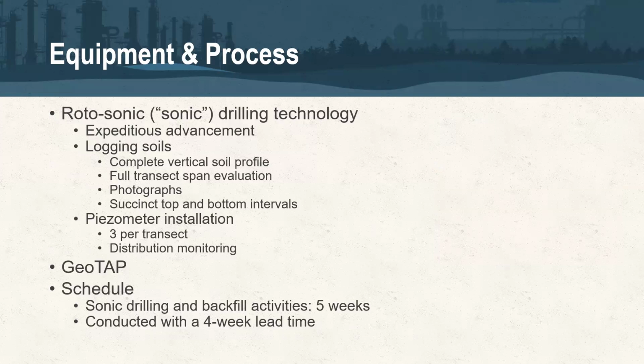We did have one other challenge at this site. We did have to install this into a heterogeneous glacial till and also a fairly hard sand unit that overlaid it. And so we elected to do this with rotosonic drilling. So we used a process here we call geotap, which I won't get into too much in this presentation here, but there are materials on our website and YouTube that talk about it.